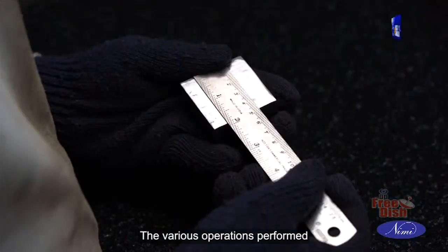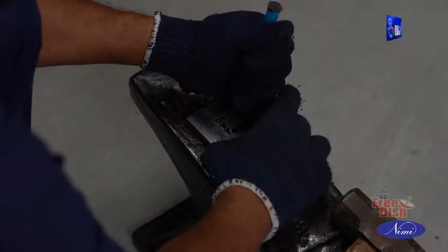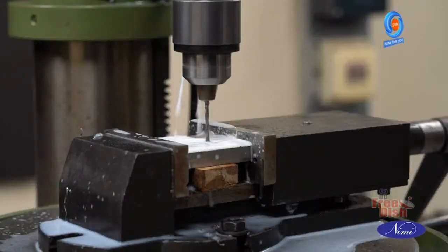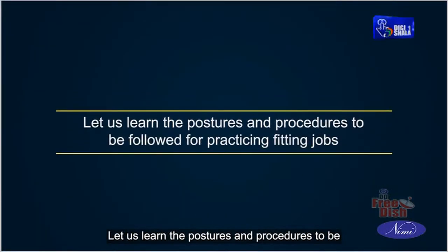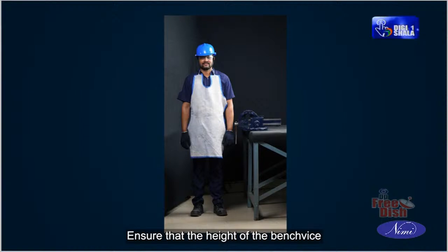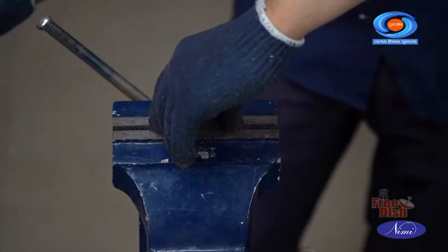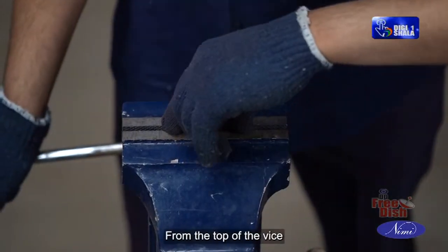The various operations performed in a fitting shop are marking, chipping, sawing, filing, scraping, drilling, thread cutting, etc. Let us learn the postures and procedures to be followed for practicing fitting jobs. Ensure that the height of the bench vise is around the waist height of the user. Hold the job in the bench vise with a projection of minimum 5 to 10 mm from the top of the vise.